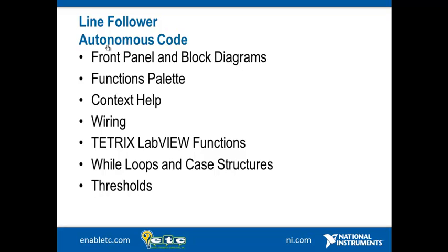First is front panels and block diagrams. And Greg referred to those quickly when we were looking at the sample autonomous code. But we're going to go into a little bit more detail, particularly about the block diagram. We're also going to talk about the functions palette, the context help, how to wire up Tetrix LabVIEW functions, while loops and case structures, and we're going to talk a bit about thresholds as well.